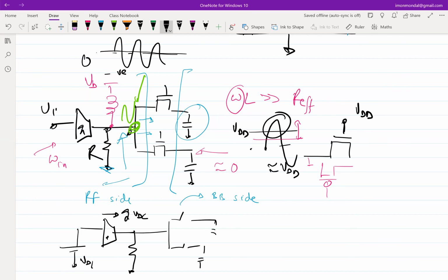So normally when you do common source amplifier design, or when you are biasing anything for saturation operation, this translates to saying that for the same COX, you are getting lower GM in PMOS than in NMOS. Does that make sense? For the same oxide capacitance, COX times W by L, the total capacitance, let's say the same CGS, you are getting lower GM in a PMOS than in an NMOS, which essentially translates to saying that PMOS has a lower FT than an NMOS. So PMOS is a slower device than an NMOS.